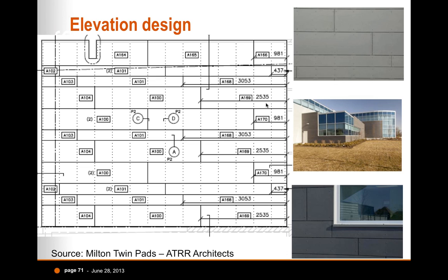So we ended up putting in vertical girts every 300 and then staggered the joints. If you look carefully, this is a matter of about 4 or 5 different part numbers mixed up in a variation. That mixing it up made sure that we had very high panel utilization, so we didn't have a lot of waste. And that's the kind of thing we can do with you because we understand the product so well. We can work with you to get what you want.